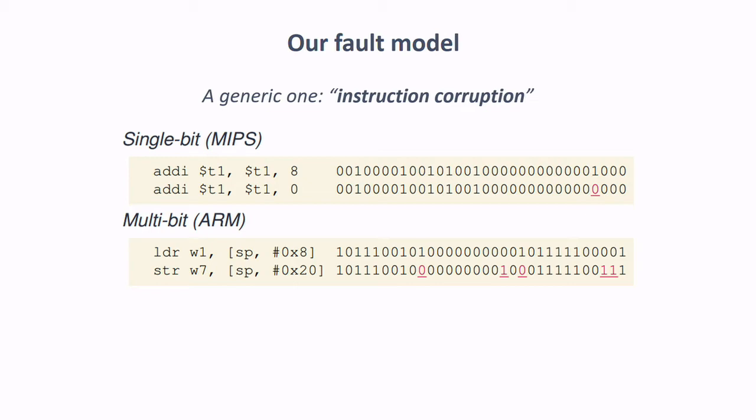So if in our attack we are able to flip that bit, then the instruction which is executed actually changes. Of course, we cannot control how many bits are flipped. So even in the case of ARM, it might also be possible that multiple bits are flipped, and instead of a modification on the operand, you actually change the instruction. So instead of a load, it will turn into a store. Again, we don't know, but in our modeling, we think that these things may happen.